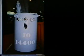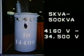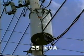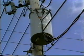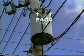Single-phase pole-type transformers are built in standard sizes of from 5 kVA up to 500 kVA and are used on primary systems of 4160 volts up to 34,500 volts. For example, we see here a 25 kVA single-phase transformer applied to a 13.8 kV Y-connected system. The voltage across the primary winding is the line-to-neutral voltage, about 8 kV, and the secondary output voltage is 240 volts.